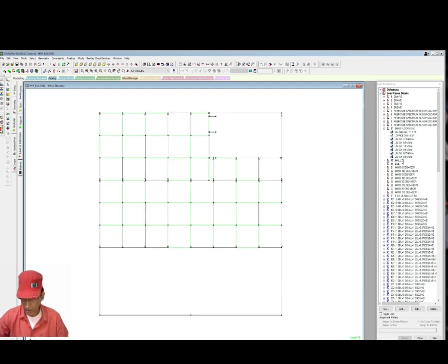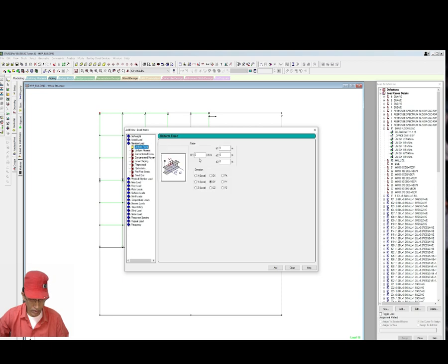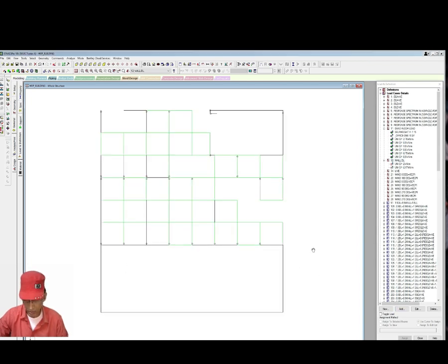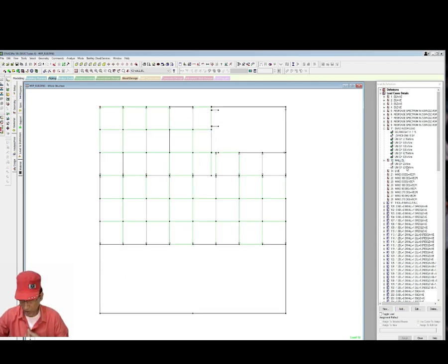Now click on wall load number 12, that is wall load. Add member load minus 2 kilonewton per meter. This will be along Z direction, and then minus 2.17 kilonewton per meter. Add, this will be along X direction because the wall height is varying here, so we are having a greater weight of wall on the average.